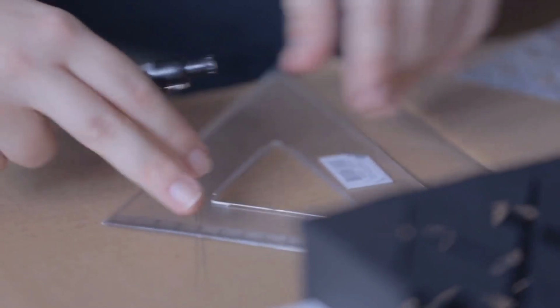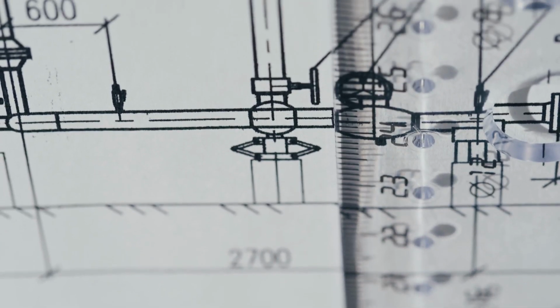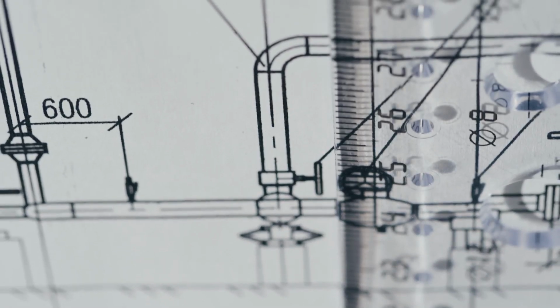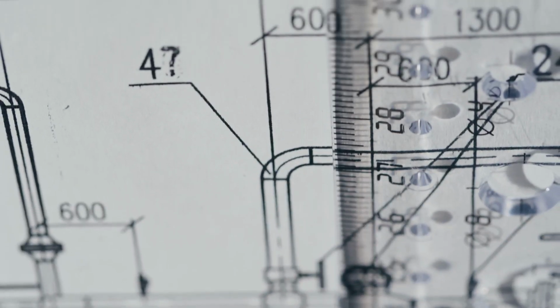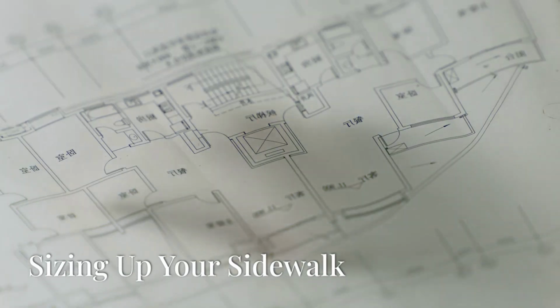For instance, if the scale is 1/4 inch equals 1 foot, you can use a ruler to measure the blueprint and then multiply by the scale factor to get the actual size. A scale of 1/4 inch equals 1 foot means that every 1/4 inch on the blueprint represents 1 foot in real life. This allows you to accurately gauge the size and placement of different elements, ensuring that everything is built to the correct specifications.